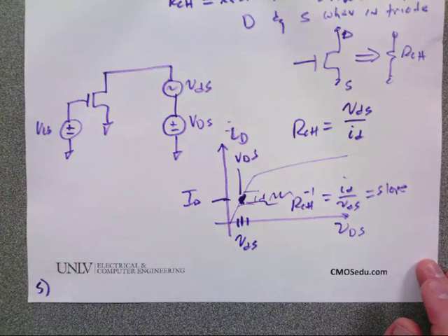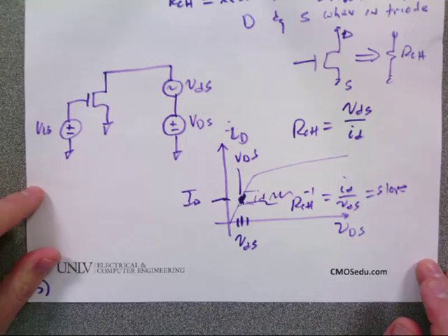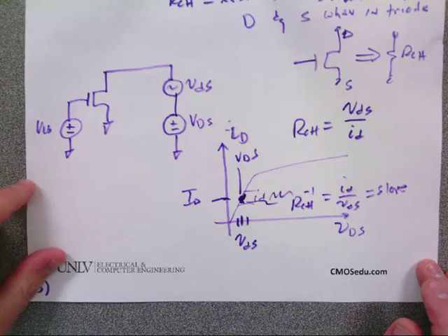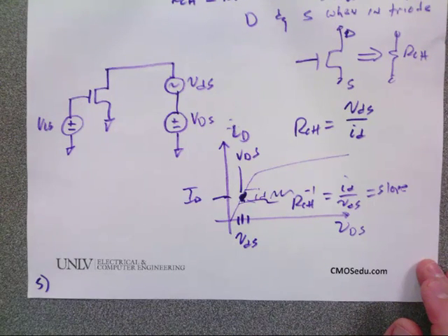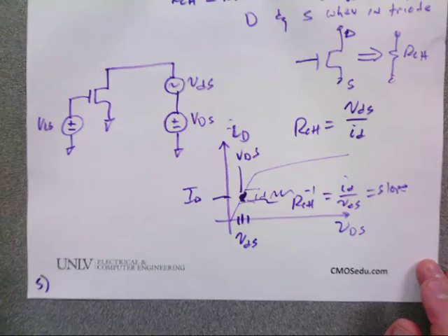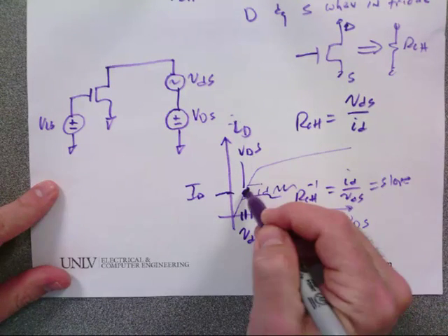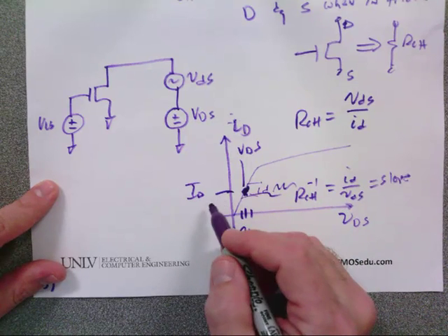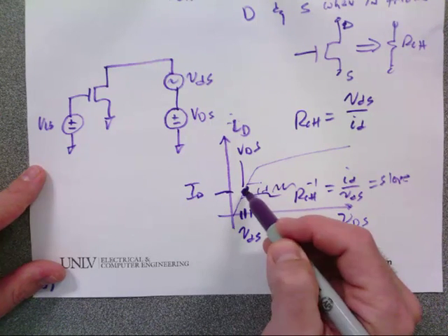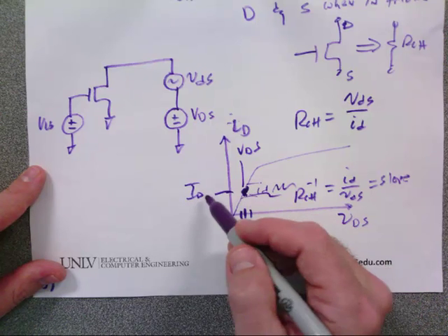Questions? Now I've got to calculate it, right? Does everybody understand what I'm doing? So now when I change the pressure, if I know the channel resistance, I know how much water is going to flow. In other words, if I know the channel resistance and I apply a voltage, I'll know how much current flows.